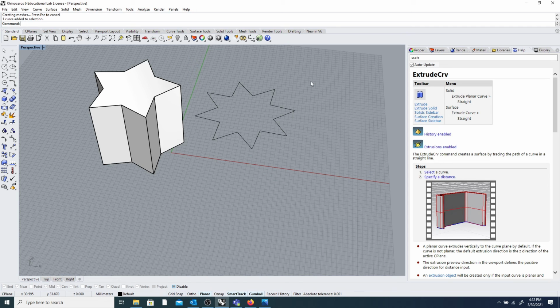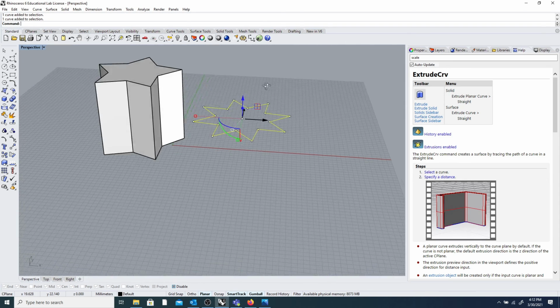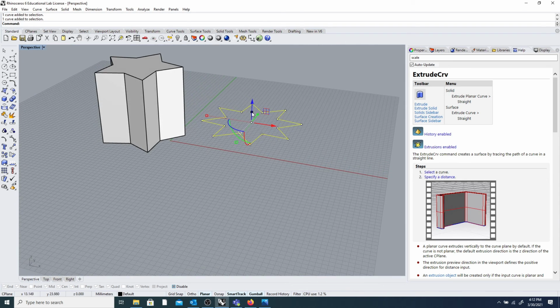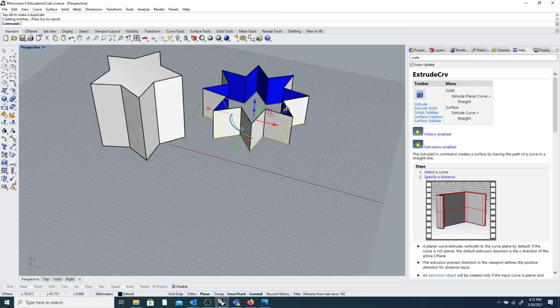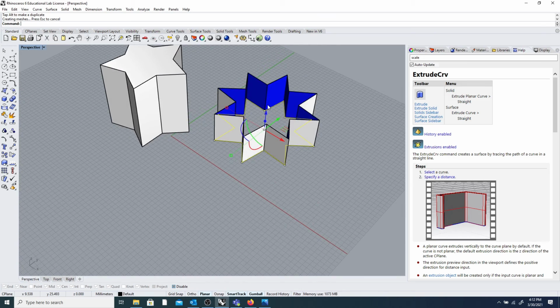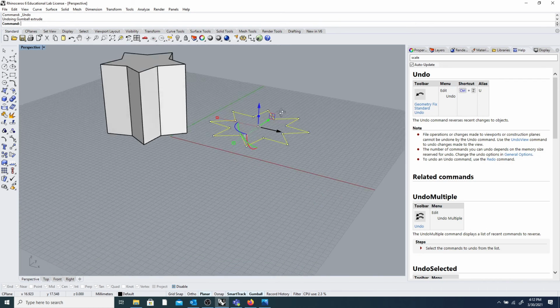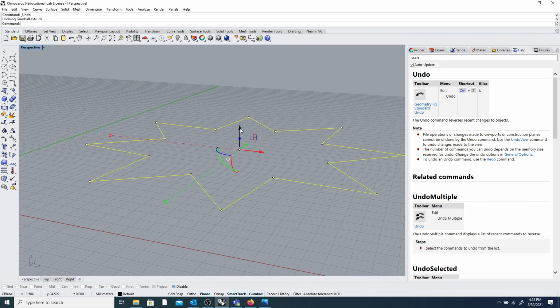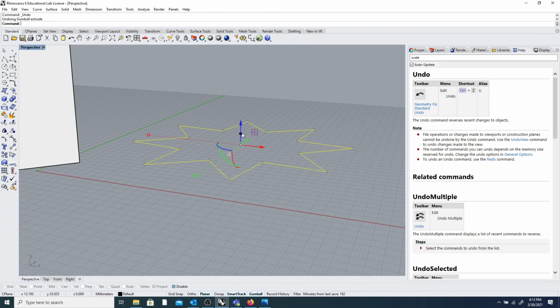So as long as it's closed, that's a really important distinction to make, first of all. And so you grabbed the blue arrow and dragged it up, yeah? Like that? Okay, so yeah, I took that curve and I extruded it by using the gumball. So when I click on this curve, it gives me this little dot on the z-axis.